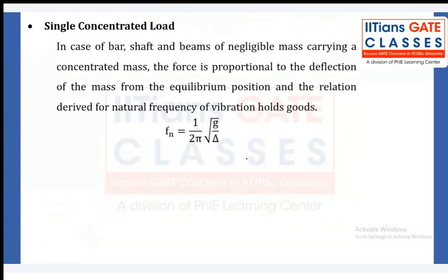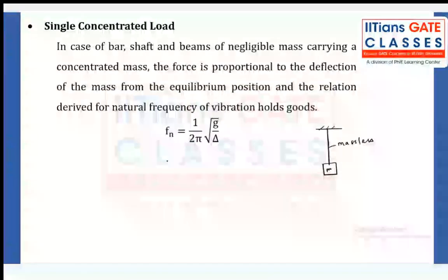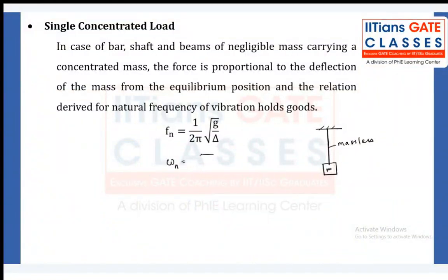No, done. Further concept. Whenever we have a single concentrated load in the case of a bar, shaft, or beam which has negligible mass and is carrying a concentrated mass, for example a massless rod carrying a mass m, then what is the natural frequency of the system? It is root of g by delta static.